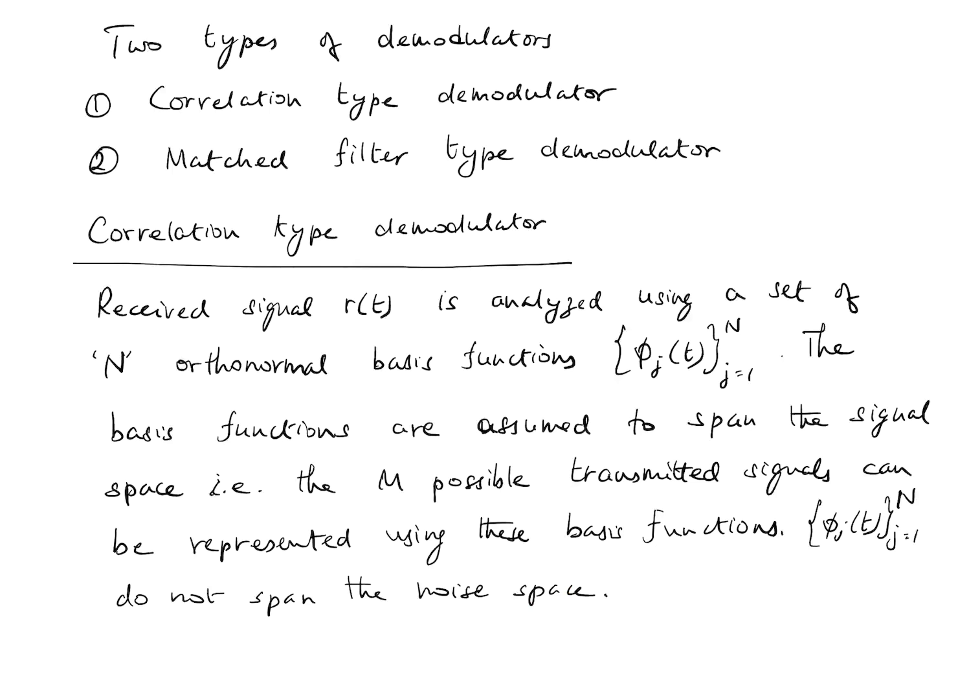Okay, because the noise signals are random and each waveform is going to be different from the other noise waveforms. So therefore, the n basis functions do not span the noise space. That has a consequence in terms of the noise that is captured by the basis functions in our representation, but we will eventually show that the noise which is missed out in the correlator does not affect our analysis, and it becomes irrelevant to the decision making process. So therefore, we can safely ignore it.